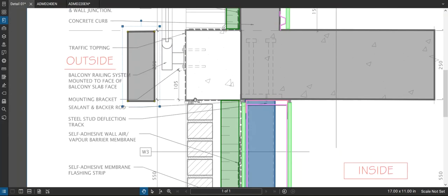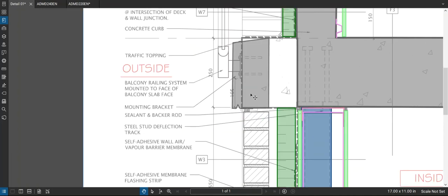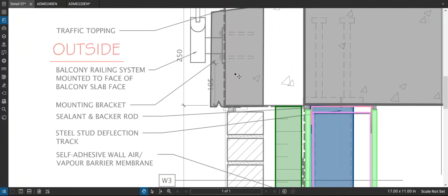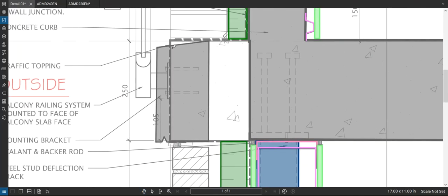Okay, so one of the basic rules is to get a drip edge on there. And so how this could be greatly improved is to do a precast cap like this, get an overhang right here, and get a drip edge in there. And then that way when all the dirt and grime is coming down here, it'll be forced to drip off and not just run down the face of the brick.